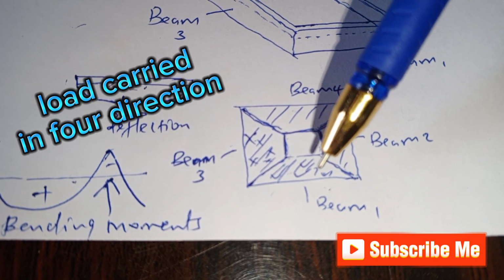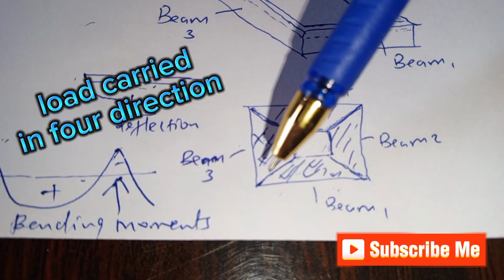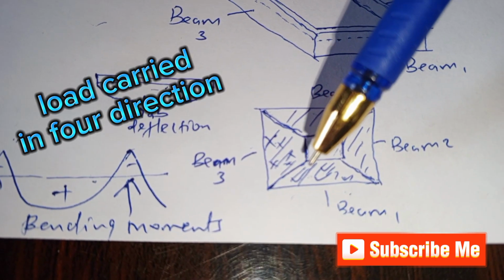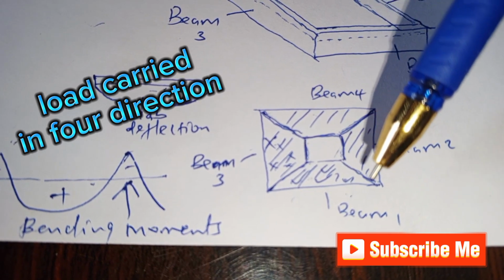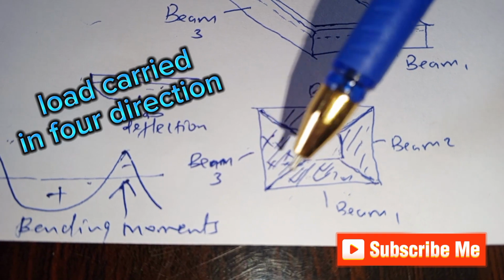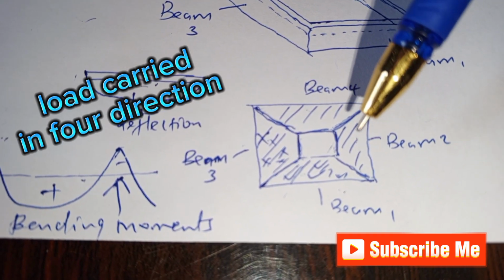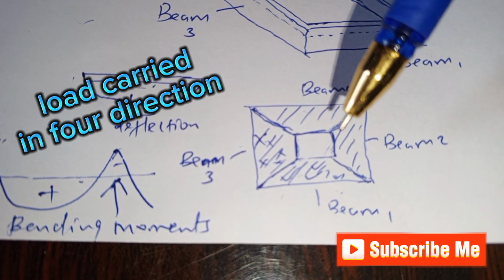Beam 1 will carry the loading as shown in this illustration. This shall be the portion that beam 1 carries, at an angle of 45. Then beam 2 will carry the loading on this portion, at an angle of 45 as well.